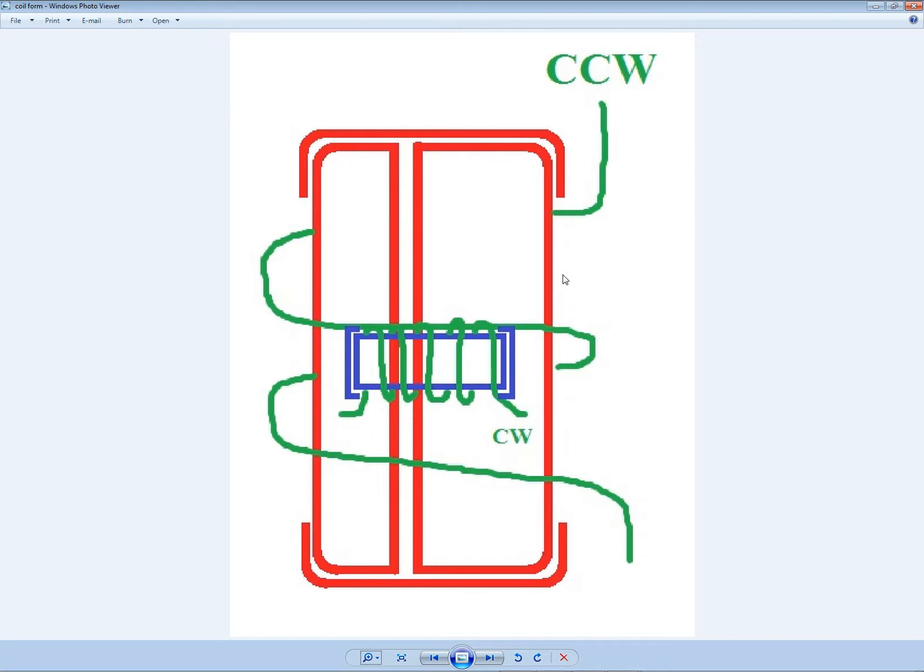Now, we could also put grooves on the outside of this tube, the bobbin, with a gap sliced down one side of the tube. We can have striations or grooves going in a particular direction, either clockwise or counterclockwise. In this example, I do it counterclockwise. And then we wrap the wire around this metallic magnetizable bobbin in the same direction, counterclockwise in this case.